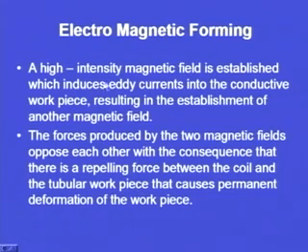A high intensity magnetic field is established which induces eddy currents into the conductive workpiece. So the workpiece here is a conductive workpiece. The eddy currents result in the establishment of another magnetic field. So a magnetic field will be produced because of the eddy currents that are being generated. The force is produced by the two magnetic fields. So now these two magnetic fields will interact.